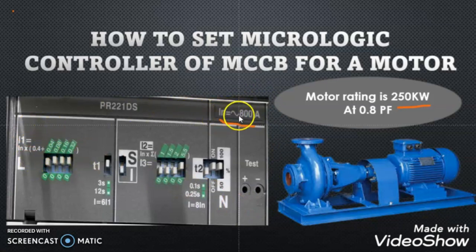This breaker can handle up to 800 ampere of current, but by adjusting the dip switches of the L setting, we can make this breaker a 400 ampere, 500 ampere, or 600 ampere breaker based on our setting. So what is the advantage of that?